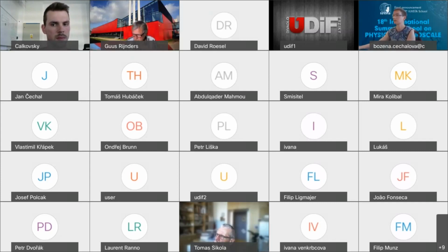But this large area deposition tool that we are using, we typically use it for materials like I have shown, like PZT and others. It doesn't make so much sense to do RHEED control for a micron-thick layer, so usually it's not even switched on. It was only switched on to make these control layers, these single monolayers, to see the crystalline quality. But that is just stationary, and not for real thickness control. Right, that speaks for itself.